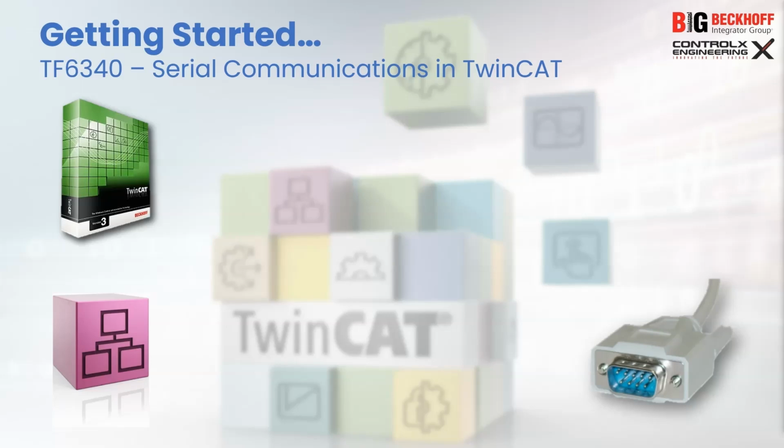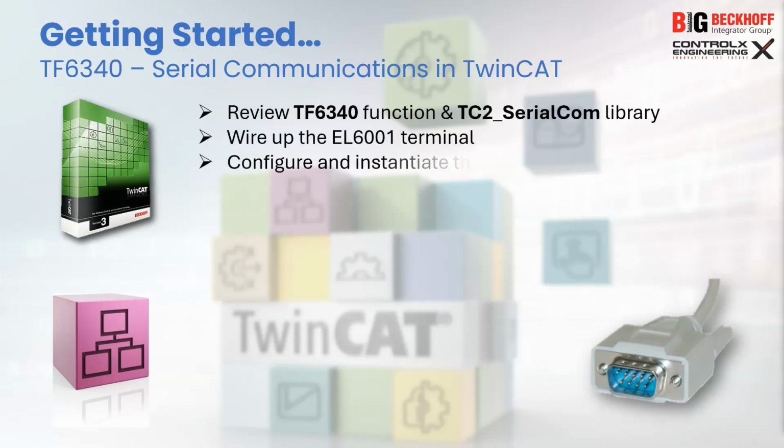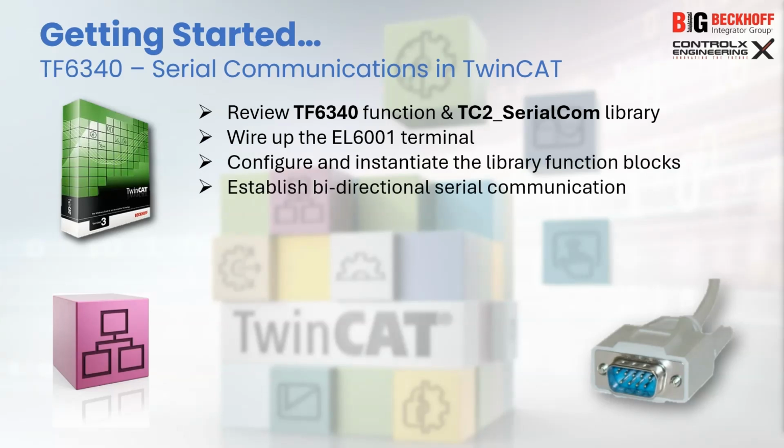We'll walk through all these steps, from wiring and configuration to writing the PLC program that sends and receives data over a serial line. By the end of this tutorial, you'll be able to confidently integrate serial devices into your Beckhoff PLC projects. We'll review the TF6340 function and the serial communications PLC library, show you how to set up an EL6001 terminal for serial communication, configure and instantiate the library function blocks in your PLC project, and send and receive data over the serial bus using structured PLC code.